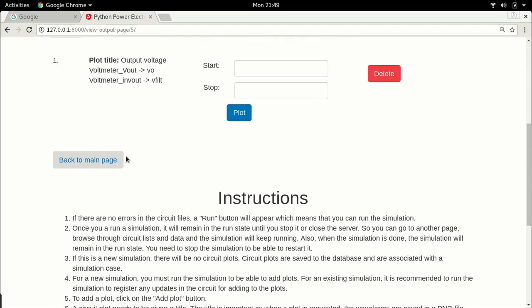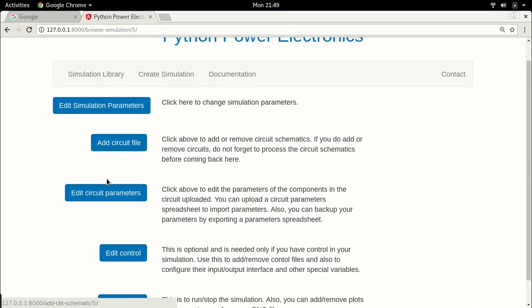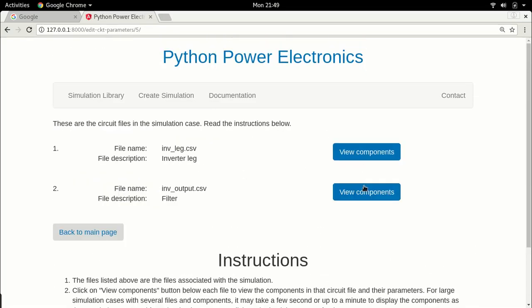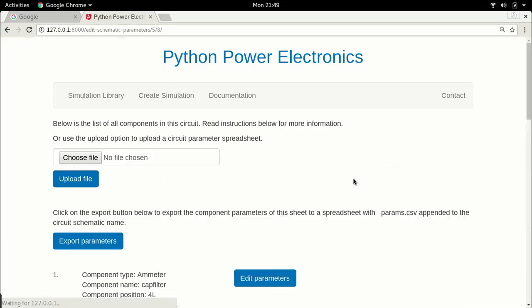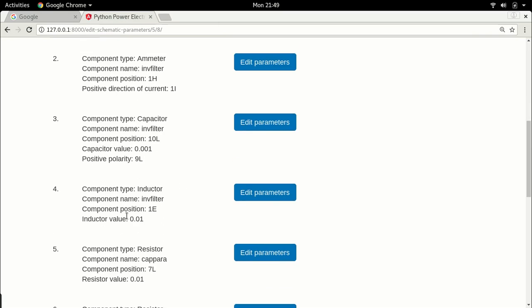Now, if you have any practical experience in power electronics, that is, if you've been building power electronic circuits, anyone who builds a power electronic circuit, if you tell them that you're using a 10 millihenry inductor, they will scream. Alright, this is a totally impractical inductor. This is huge, extremely bulky, and you cannot design any power supply with something like this.